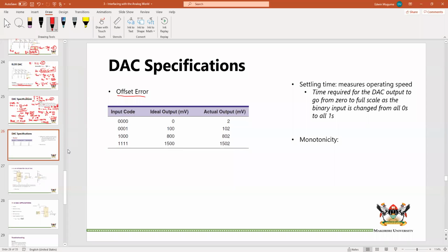It means that if I'm going to buy something like salt, and before they start putting the salt, the weighing scale already measures 0.5 kilograms. They are going to add 1 kg, and it would read 1.5 kilograms. The problem is that if they look at 1 kg, it means that they've actually given you only 0.5 kg of salt. This is going to be caused by the offset error.